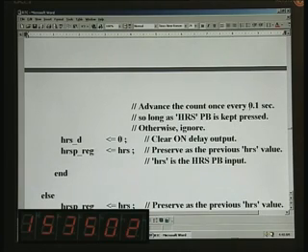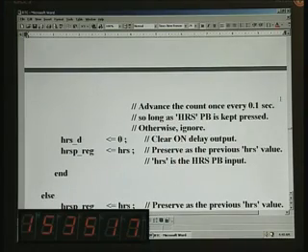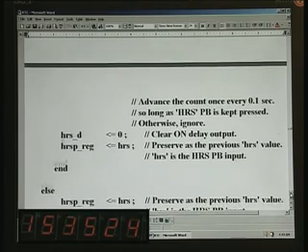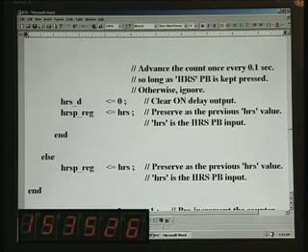So 0.1 is the time base, so 20 you are trying to count. Each time, what we have seen is merely incrementing when the condition is 0.1 second. Whenever a 0.1 second condition occurs, you merely increment this counter, and when it is equal to 20, stop that. We have forced it to 0, you remember this, and here also clear on delay output, preserve as the previous value, this also you have to do, okay. So is this making sense, okay.